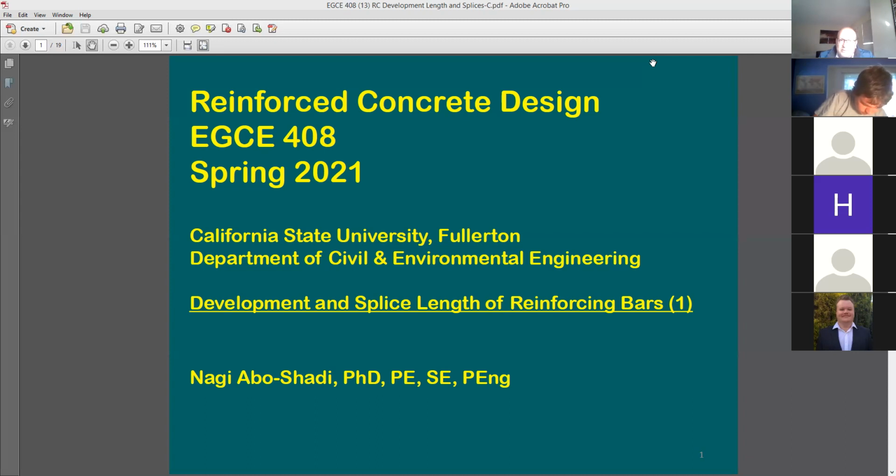How much is the soil bearing pressure? Was it given in the project statement, or was it given in this specific problem submittal? It's in the statement. It's 3,000 psf. 3,000, very good, all right. And I guess you have enough slides and enough examples to be able to do a complete design for one footing. This will include sizing the footing, and then after that, the reinforcing at the bottom of the footing.